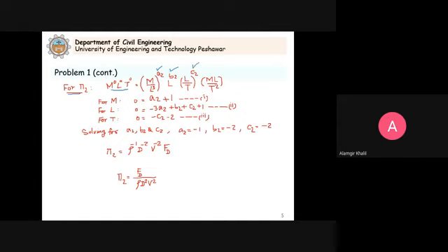You can write down x, y, z. Really doesn't matter because we calculate their values. So again we go for M, for L and for T. We make these expressions. How? We satisfy the dimensional homogeneity. Clear? So you calculate the values of these exponents and then you put them back here and you simplify.